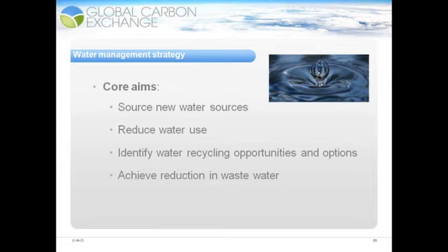You may also want to identify water recycling opportunities and options. Whether you are a car wash who's washing cars and all your water is going back through the drain, through a grease trap and then back to the sewers, you may want to take that water after the grease trap and recycle it and bring it back into the process such that you reduce your dependency on the municipality supply and you actually conserve on water as a whole.